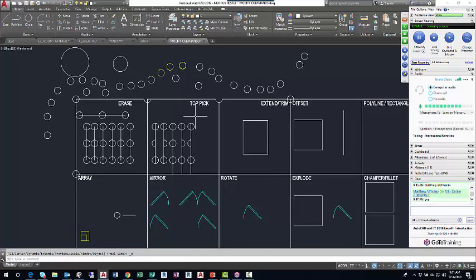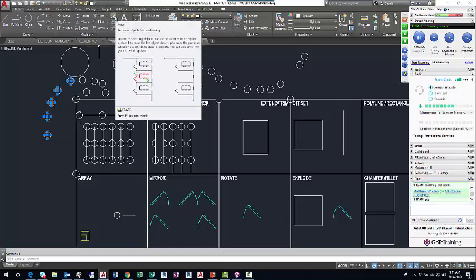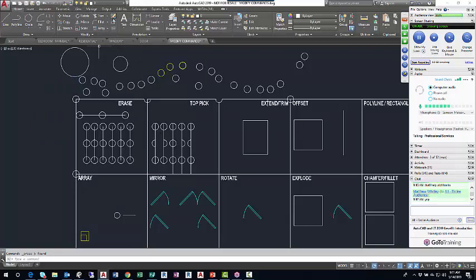And just as a refresher, one of the commands we talked about was the erase command, and I'll just select a few objects in my drawing, and once I have my desired number of objects selected, I'll hit the erase button on the modify panel, and those objects go away. That was one of our modify commands.